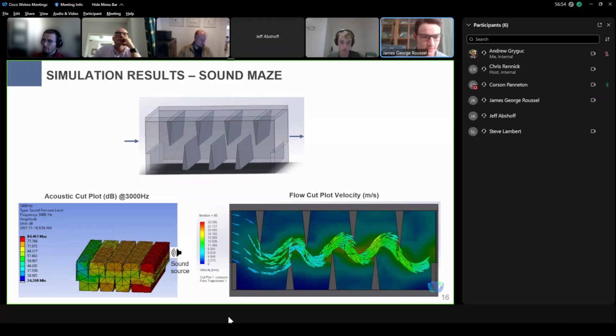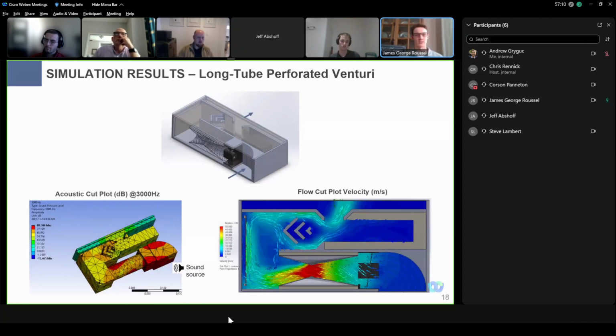Yeah, sure. So I noticed with the acoustic simulations, the meshing was quite difficult. We did add foam on the interior faces of these parts to try to damp as much sound as possible. And with that, we had some very thin features, and the meshing was really difficult for those thin features.